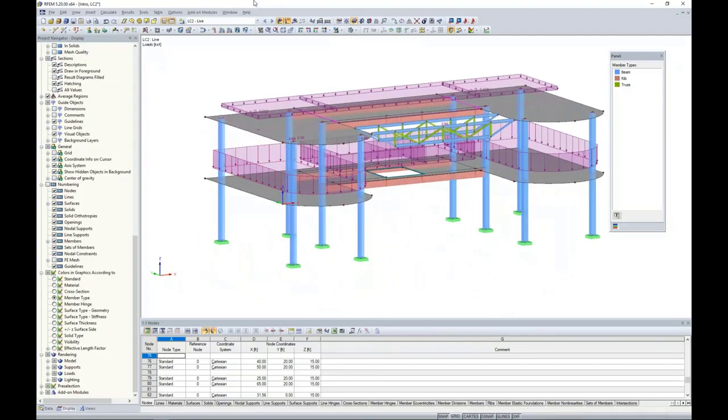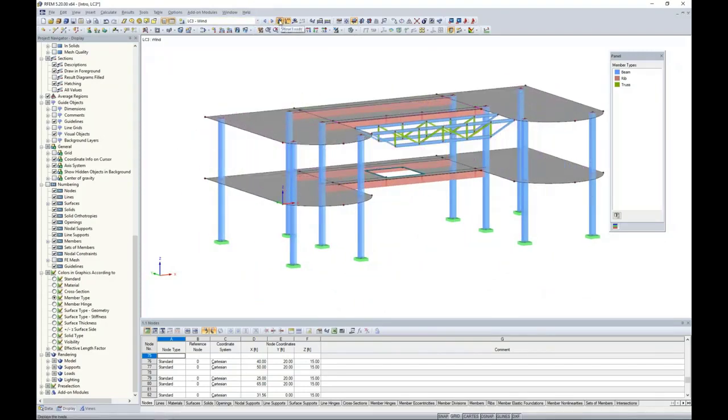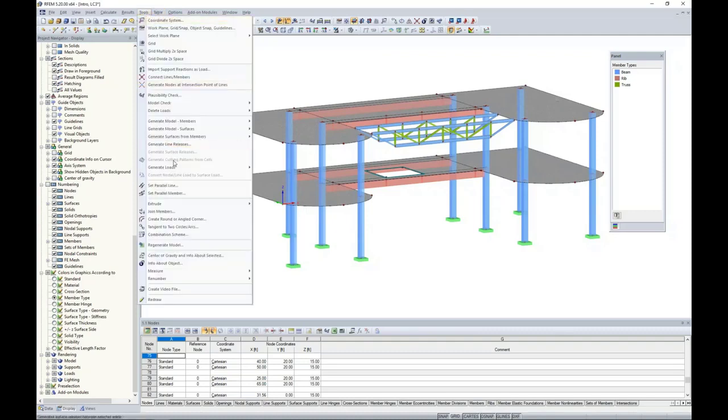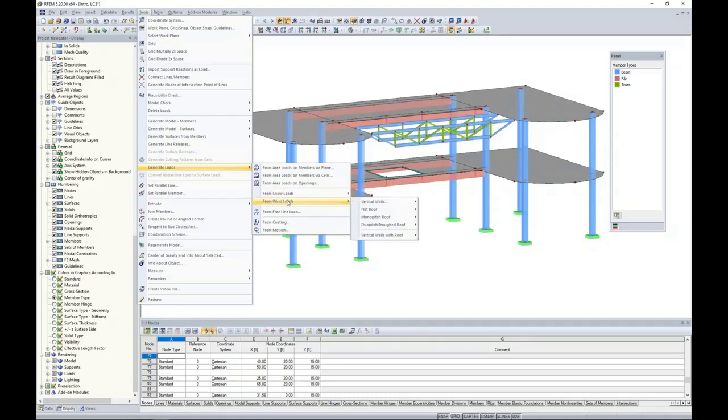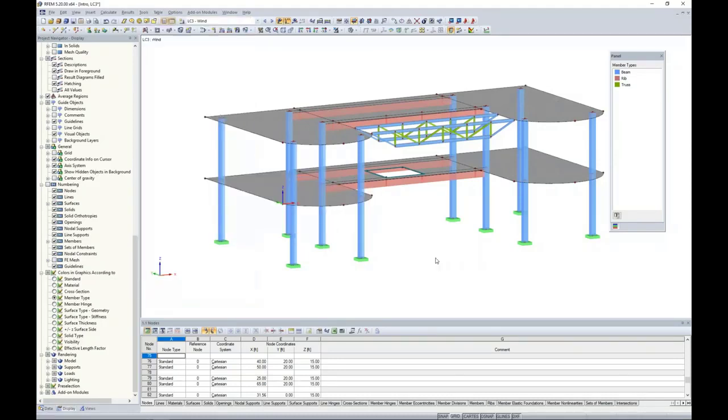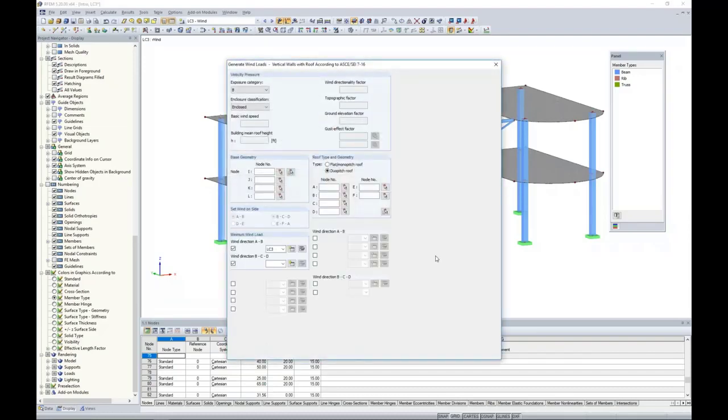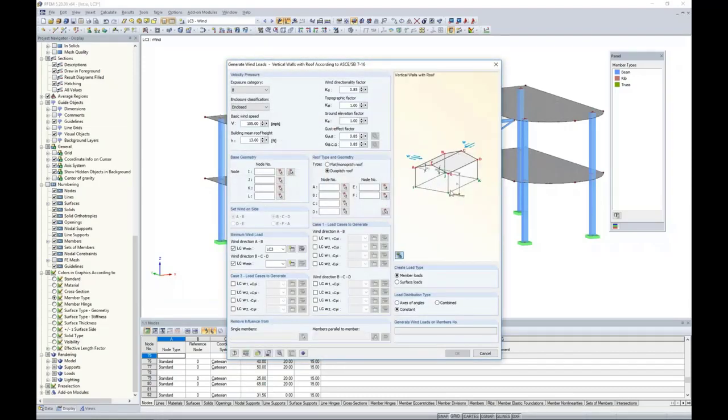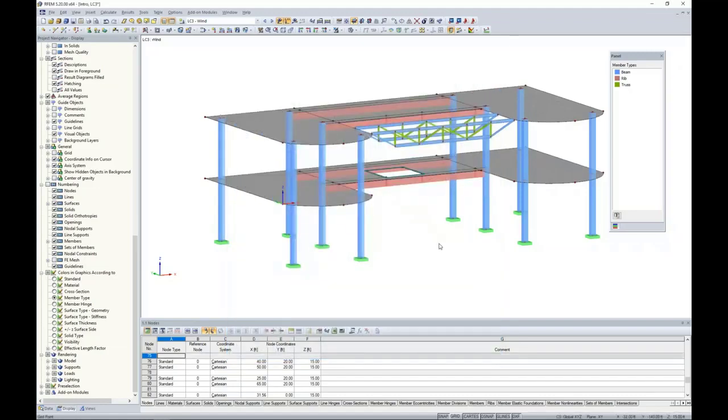Okay, so for the wind load scenario, under the Tools option, Generate Loads, from snow loads and wind loads. These are a couple of load generators, but keep in mind that we do have the ASCE 7 here. It really is only applicable for rectangular type structures such as this. The minute that we get outside of these geometric properties, then we need to manually apply the wind loads instead. So we're certainly outside of this realm for our example today, so we cannot use this generator.